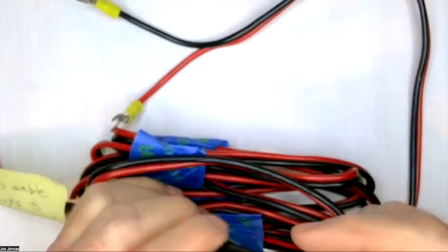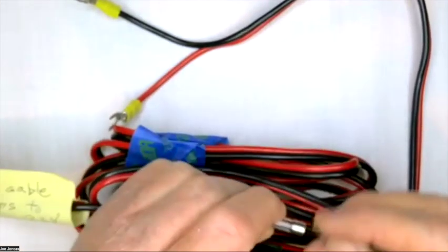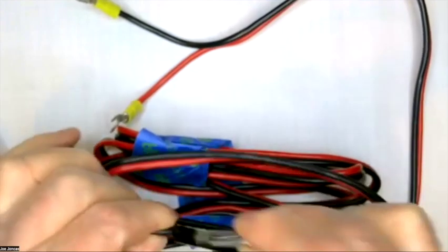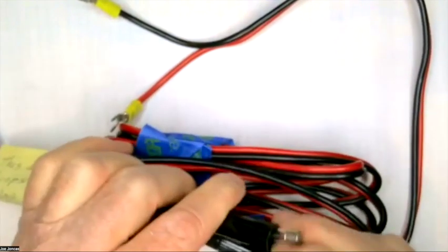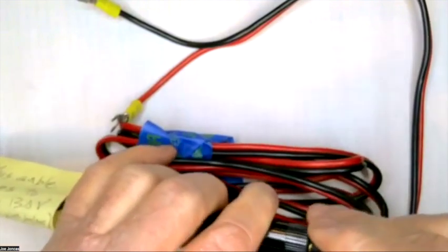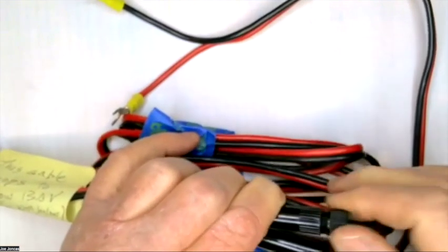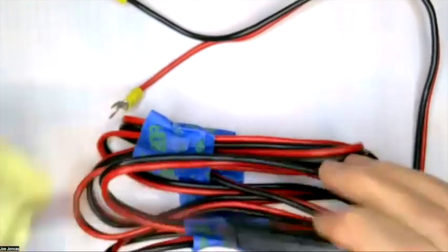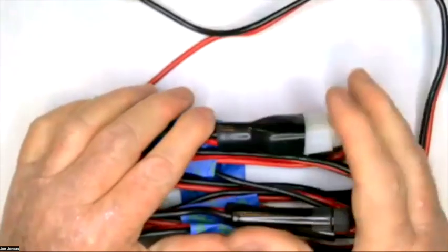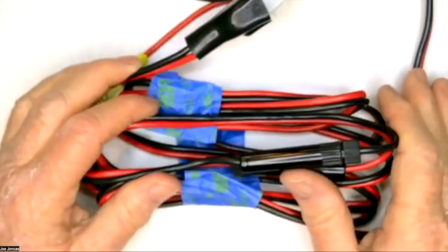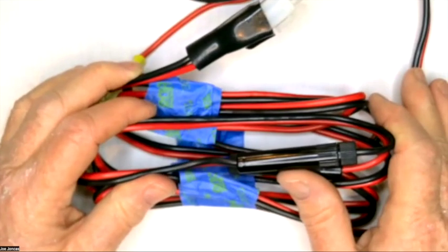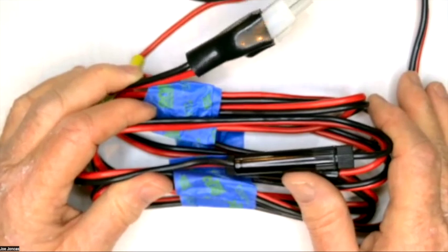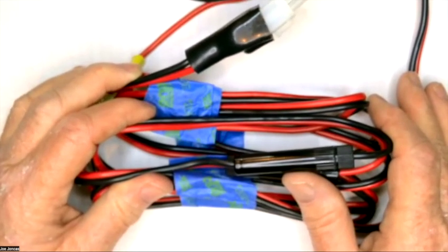See that little tip on there? It just touches the end of this fuse. And then the other end looks the same. Oops, I can't push it out. I used to be the fuse engineer at Tektronix. When you purchase a cable, first of all, the fuses are there not to protect the equipment. The fuses are there to protect the wire.